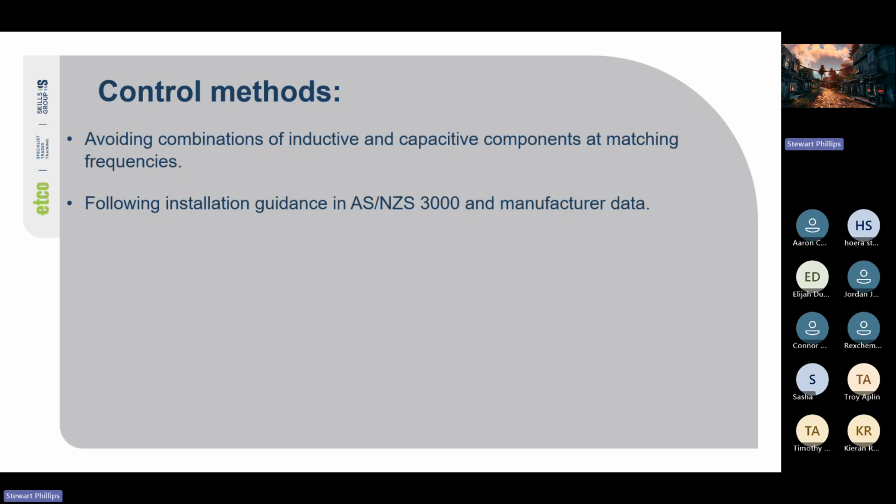So if we're using a variable frequency drive and we accidentally set the motor control frequency to the wrong one, and the inductor inside the motor and the power factor correction capacitor interact in the wrong way, or if it's a single phase cap start cap run motor, then there's a chance of the varying frequency. We get it just the wrong one when we're adjusting the speed, creating that resonant frequency.